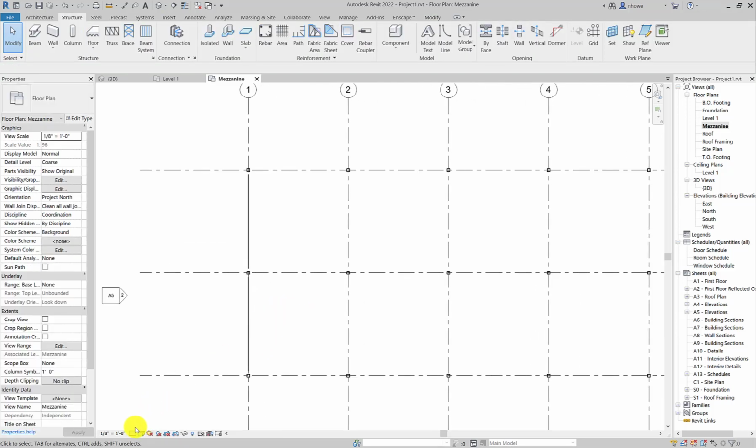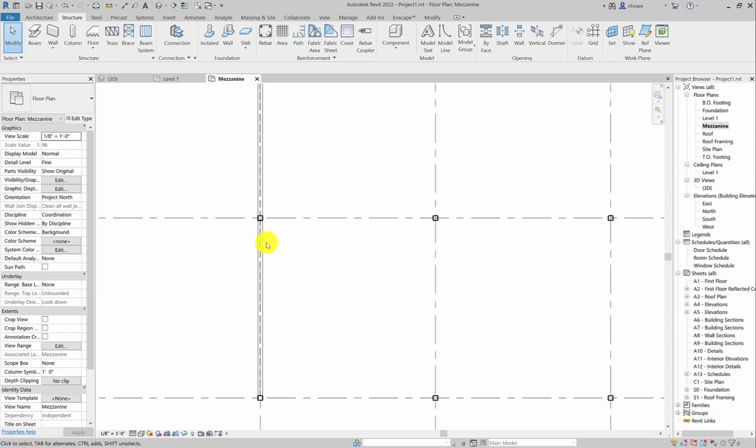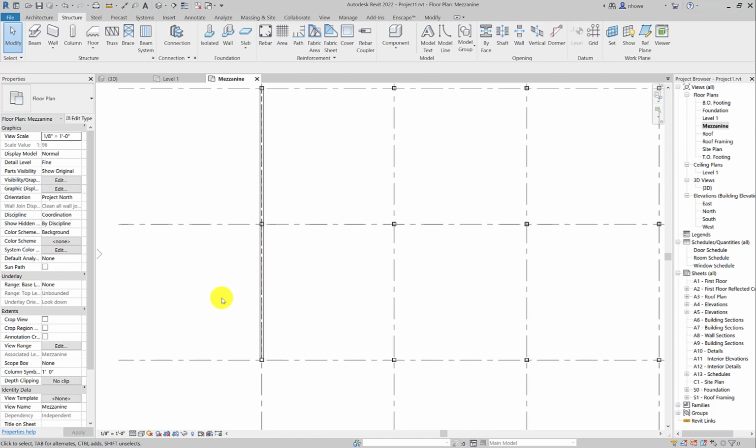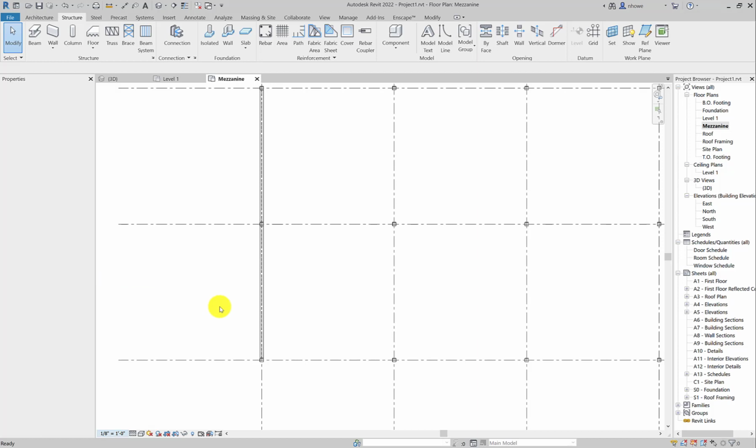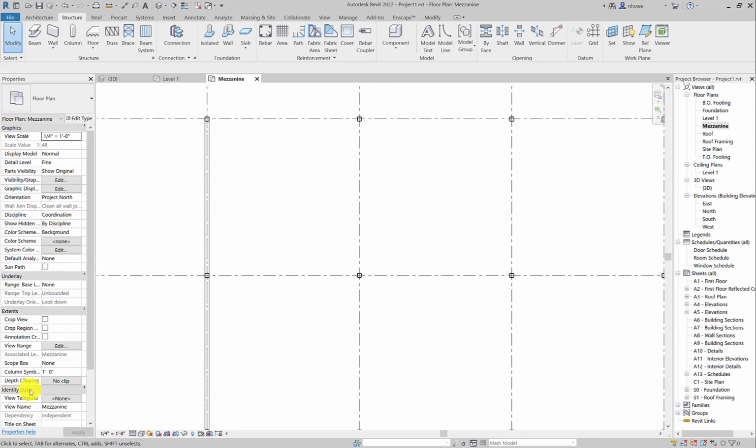For every drawing you can set a different level of refinement. So we have coarse, we have medium, and we have fine. If we move it up to fine, you can see that now it represents the beam with 2 lines, kind of more how you would draw it in actuality. So let's just roll with that, and we'll just go from there. All right.